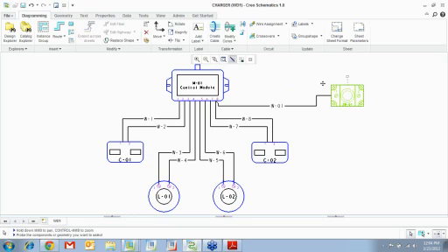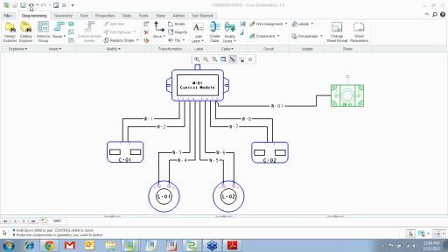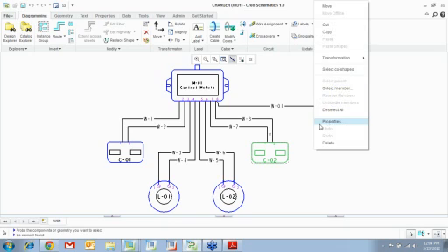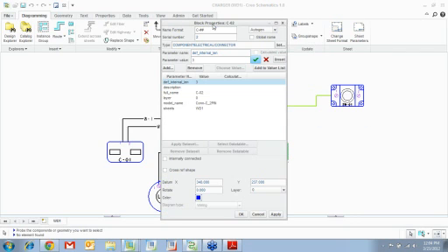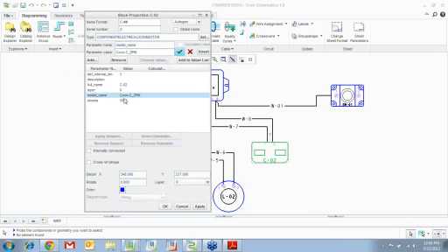We're going to select that component, we're going to right click, we're going to go to properties, and you should have a parameter called model name. Now this is a symbol that's outside, so I haven't really added that parameter here, but I can show you real quick. You select this, right click, properties, you should have a parameter called model underscore name. See that?